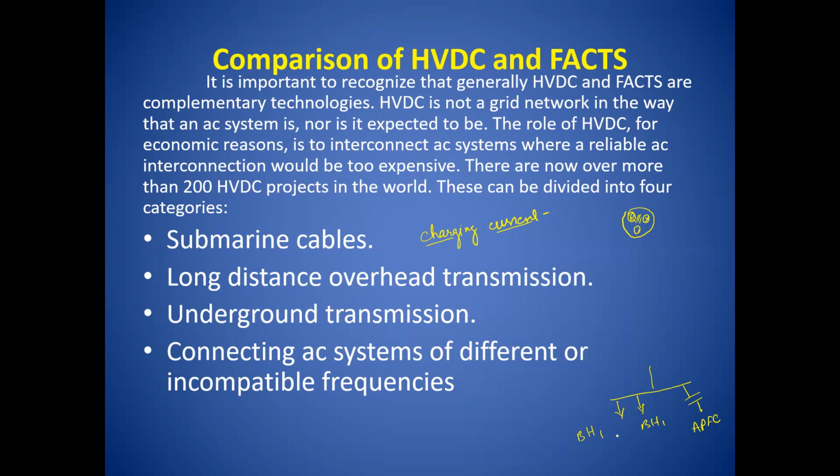It was observed that even when the automatic power factor controller was totally off, meaning not a single capacitor was in working condition, the power factor was still unity, and it is due to the cable charging current, which is a leading current.